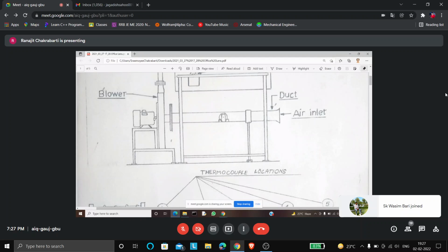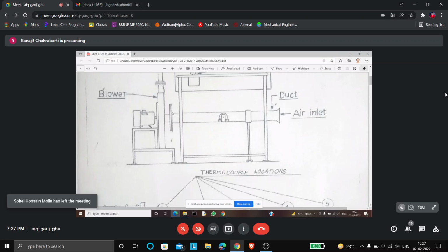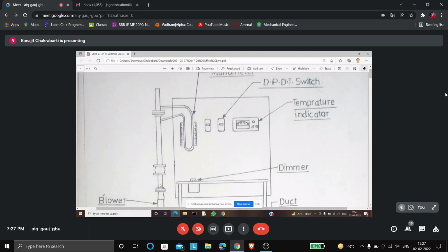There is an electric motor. When it is getting its power, it runs the impeller here, and that draws in air from the outside atmosphere through this pipeline, which is rectangular cross section, into, this is a flange you can say. This duct has a flange, and this blower also has a flange. They are connected here. So the air is flowing through this into the eye of the blower, then it is going centrifugally, it is a centrifugal blower,